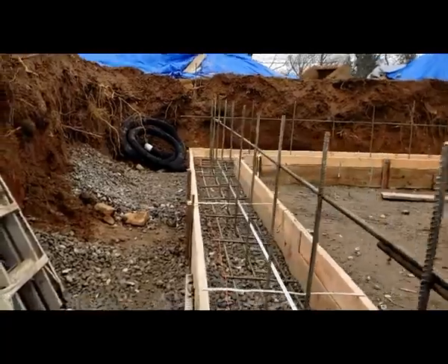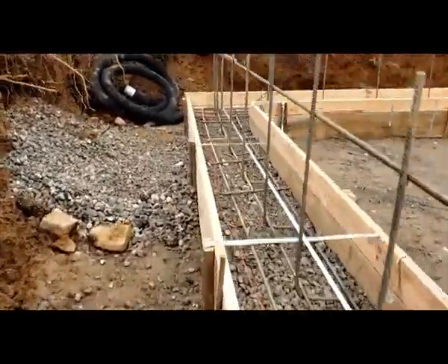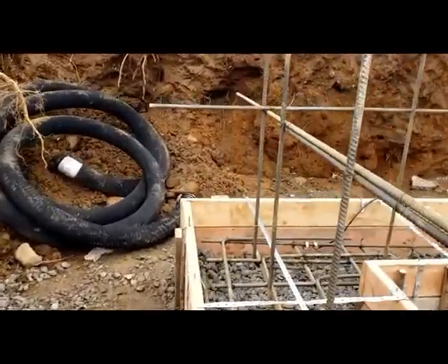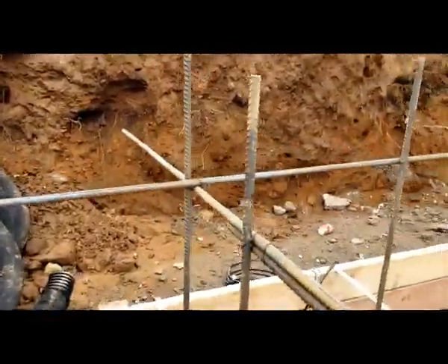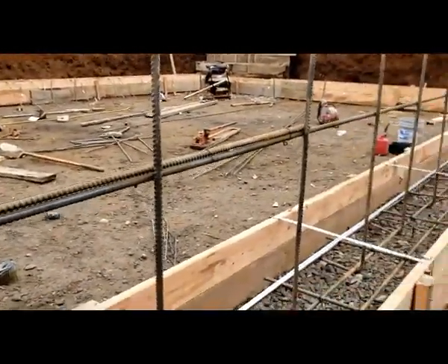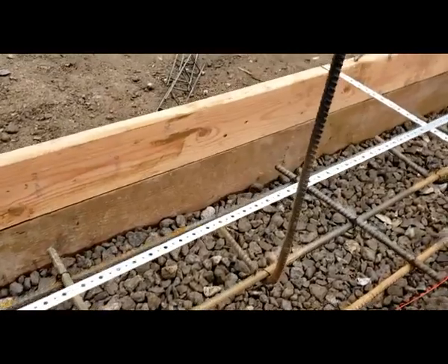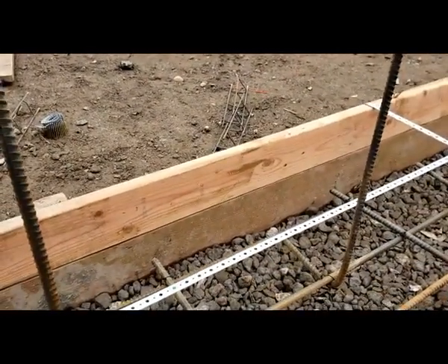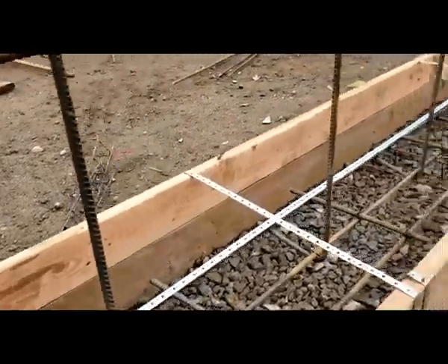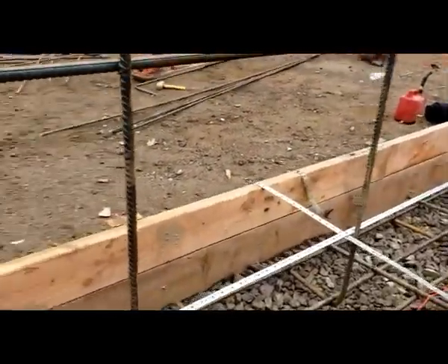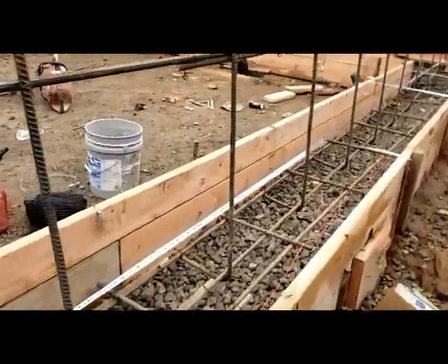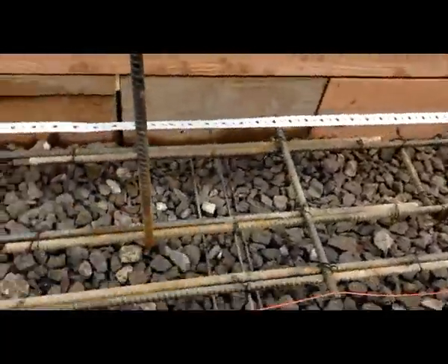Now, rebars. Most of the houses here in New Jersey, we use number 5 and number 4. Just to make everything simple, I use number 5 for all my jobs. I have horizontal and verticals. Usually 3 number 5, and every 2 feet we tie it all together. Make sure you go over the overlaps. Those are 20 foot sticks, number 5, so they overlap about 2 feet.